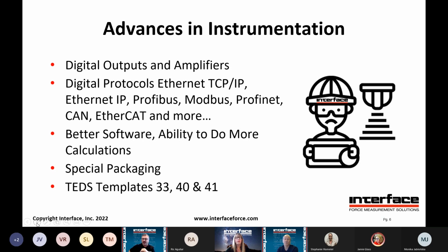Doing a lot of special packaging, amplifiers, somebody wants multiple channels and things, we can package them together. Somebody wants custom cables and custom enclosures and things, we're doing a lot of that. Doing more with TEDs, like I mentioned, there are templates that allow linearization or even polynomial fits of the data. And then, of course, if you want to do a proprietary system, anything you want on a TED chip can be read in along with the sensor connection and used to set up software that customers write themselves.